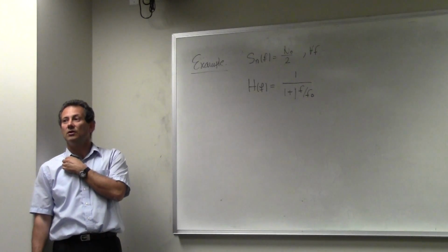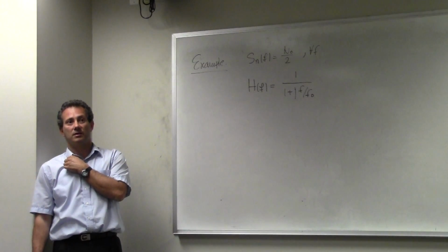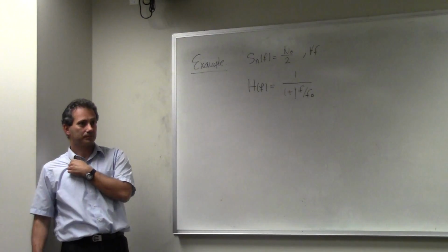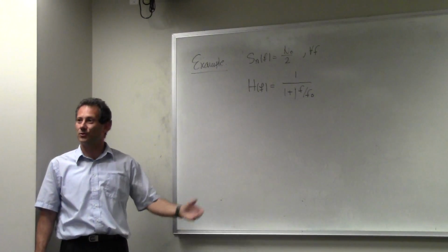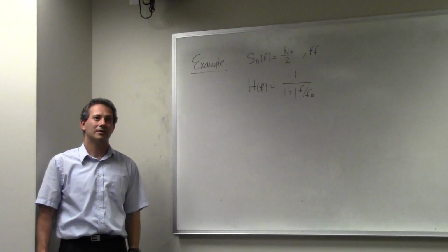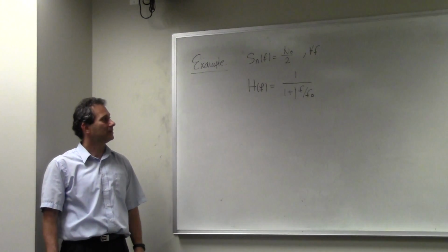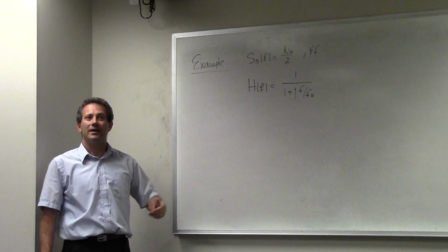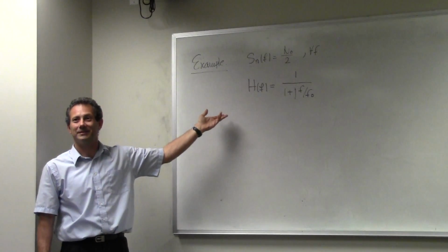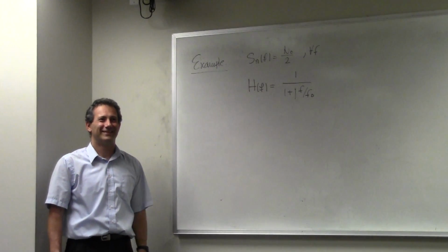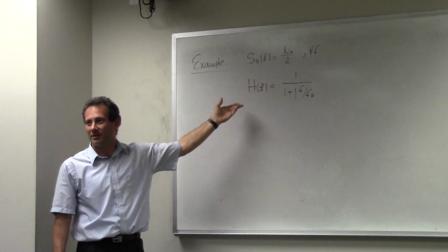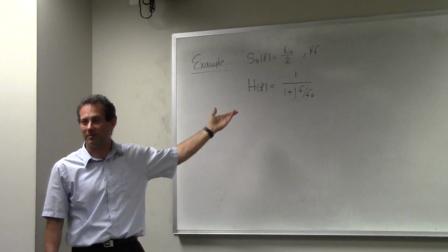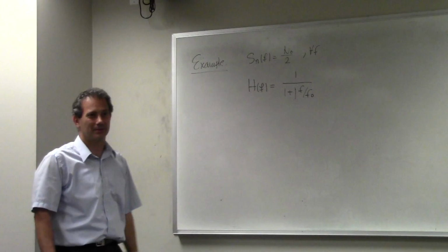So this is a low pass filter. It passes DC and attenuates high frequencies, right? What is the order of this filter? First order. First order bandpass filter, low pass filter. And what type of filter is this? So with the first order, low pass, they're all the same type, but this could be like a Butterworth filter.